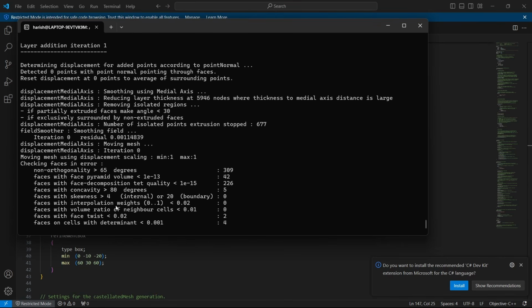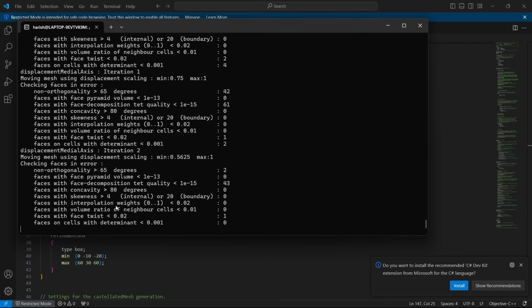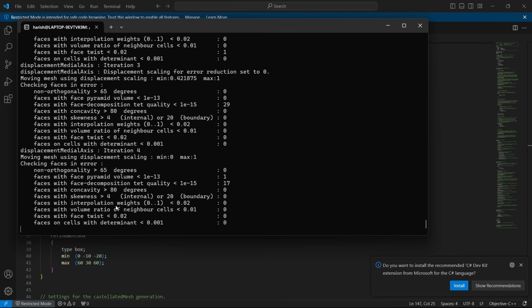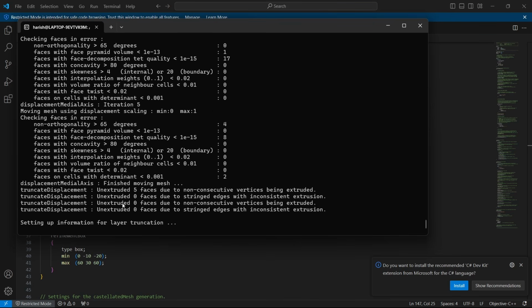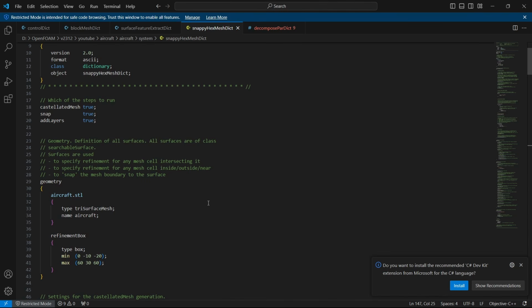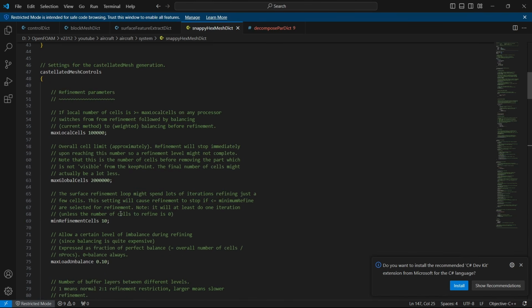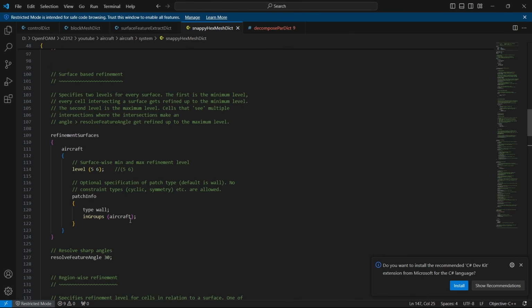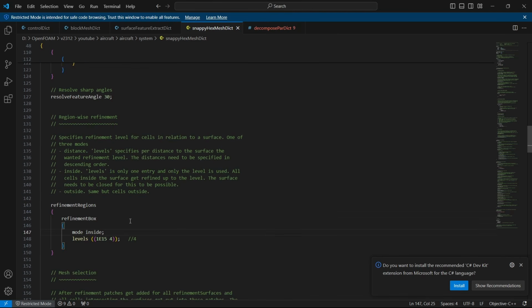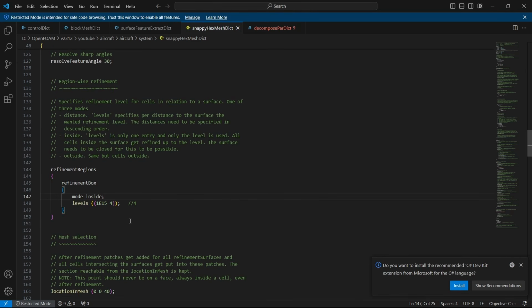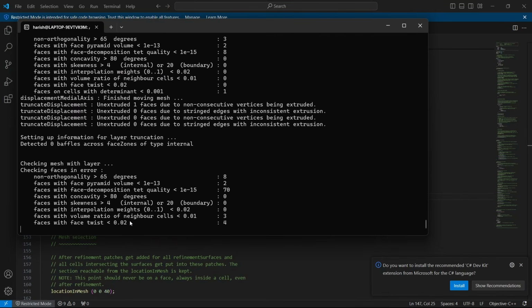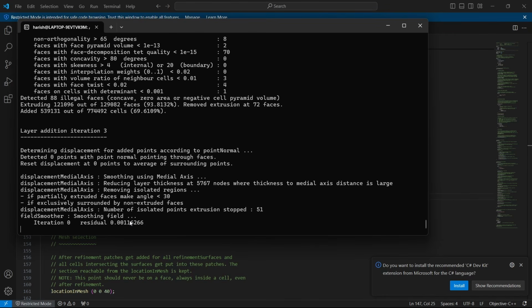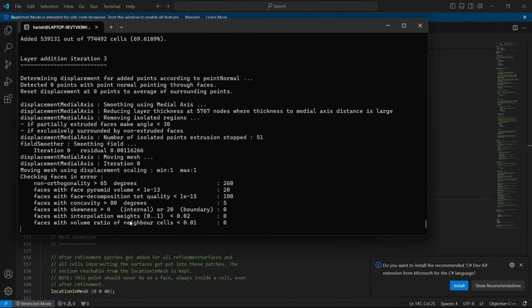While the mesh was running, it actually gave me an error that my computer could not handle that much refinement. So I actually went back to snappyHexMeshDict and changed these values, whatever we put in the comments, to the default values so that it can handle the mesh. It was not sufficient to have 8 processes alone to do this mesh. So I changed it back. Now the meshing is running, and I hope it will finish without any errors.